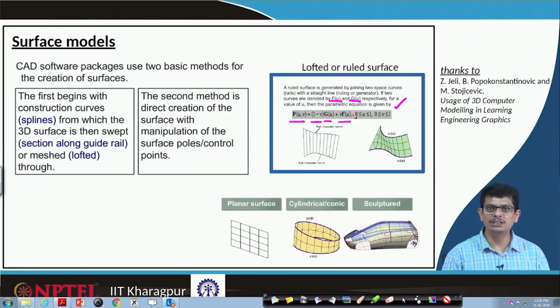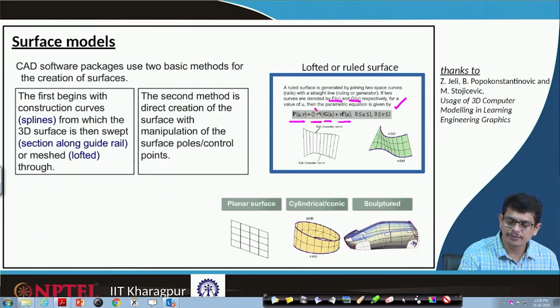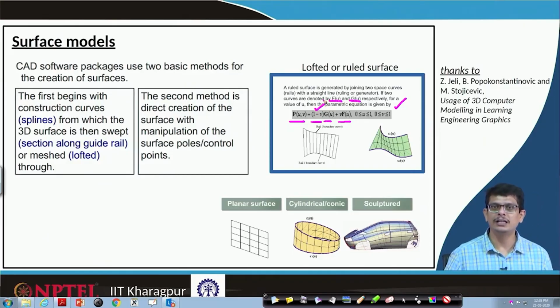It is based on how much distance you would like to really look at, something like the distance between f of u and g of u. If we are representing a fraction in terms of nu, 50% on this side, remaining 50% on that side, or 40% on this side, 60% on that side. That kind of weightage we will apply to really map these two curves by joining a line and try to construct a ruled surface. So, the whole objective at that back end, it goes in this way: you pick lines, you try to smoothly construct a surface passing through these curves.